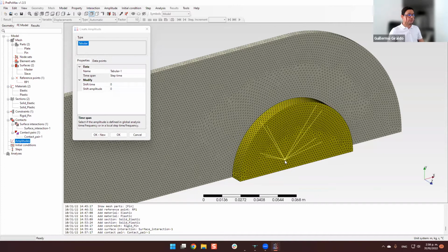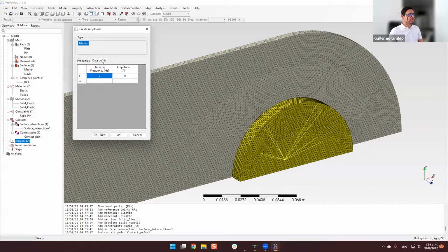But if I apply a force that will create a large change, then I can make the solver diverge. So in order to not apply the full force immediately, we will use a curve, as a function of time. In this case, it's pseudo time. At time 0, we will multiply the force by 0, and at time 1, we will multiply the force by 1.